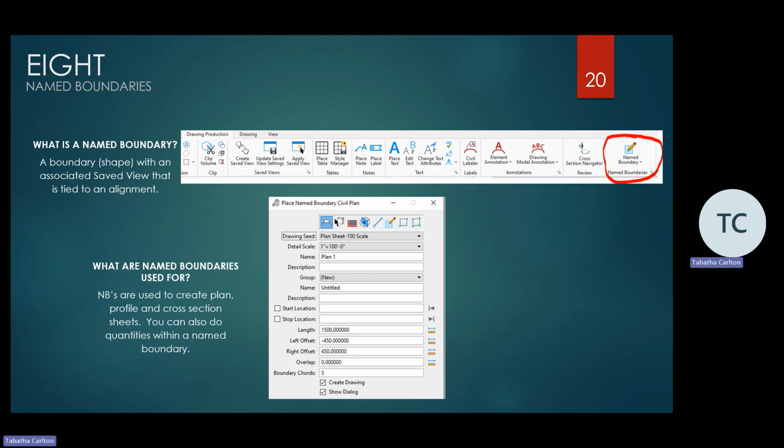but the fastest machine you can get to run it, the better. More memory, better graphics card. You also want to, depending on how long your project is, break it up into mile-long links. If you've got a 3-mile project, you're going to have 3 corridors. You may want to put your geometry in one file, but your corridors you definitely want to break up.